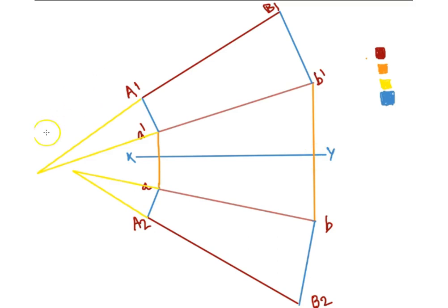What you see on screen is a typical setup where you use a plane rotation technique, or this is solved using a plane rotation method. To know more about the plane rotation method, please refer back to our earlier video on plane rotation technique, which gives you a very clear explanation using animations. As usual, the technique is to start drawing the XY line, positioning the points A dash, A, B and B dash, B.